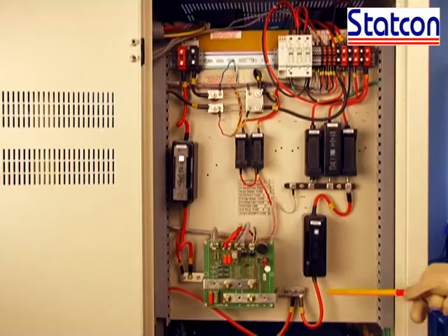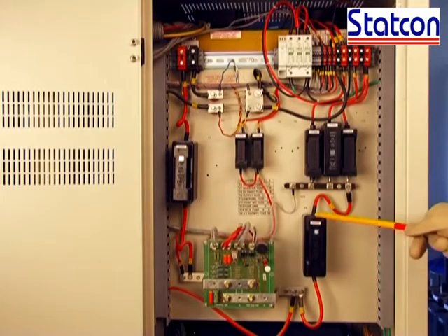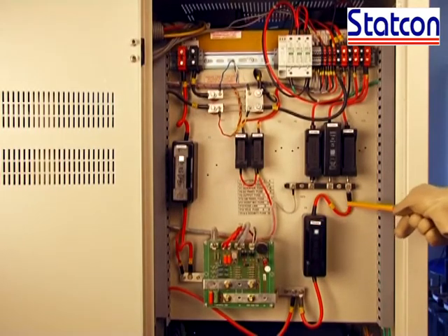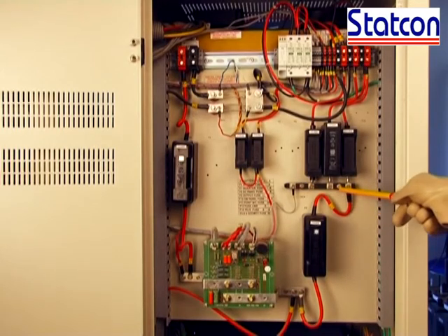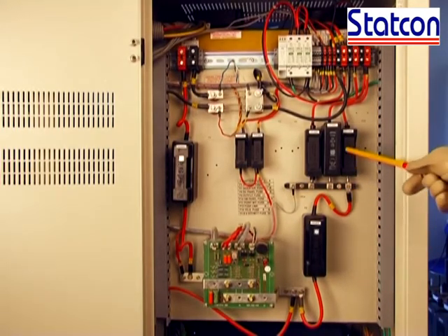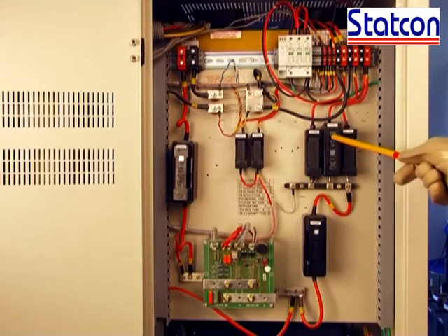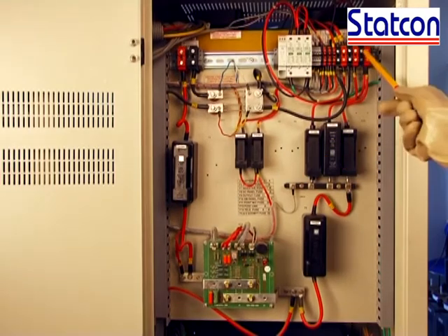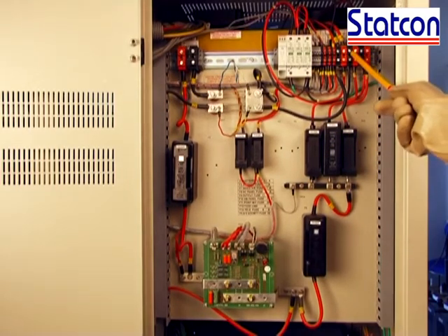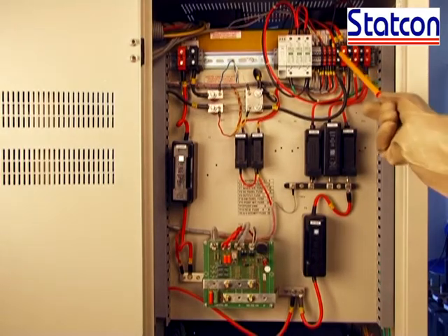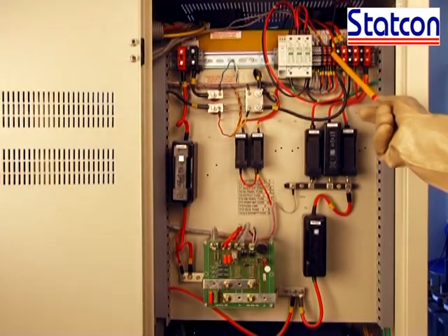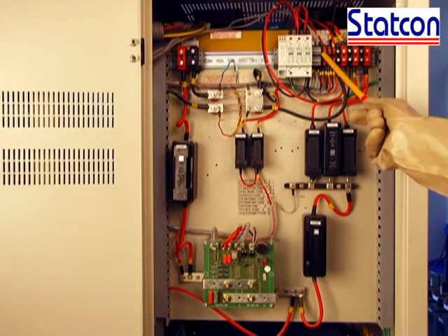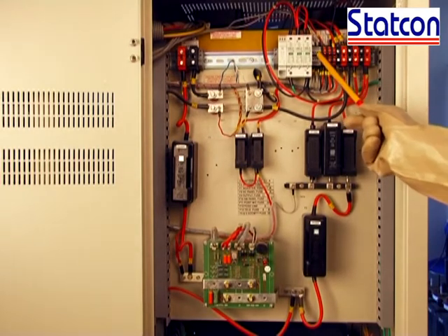The final output of all the SMRs is drawn from these wires and fed to the 80 ampere main fuse F9. Then the output of F9 is given to this strip and 3 different fuses are given to point machine, DC panel and AC panel. With this, supply goes to their respective terminals. These are the terminals through which we supply 110 volt DC for various applications like SM card, display and teleoperation.